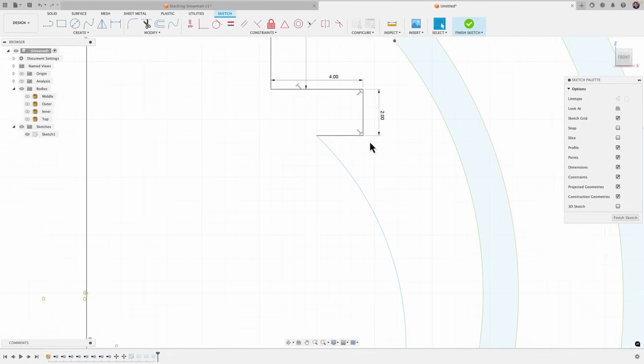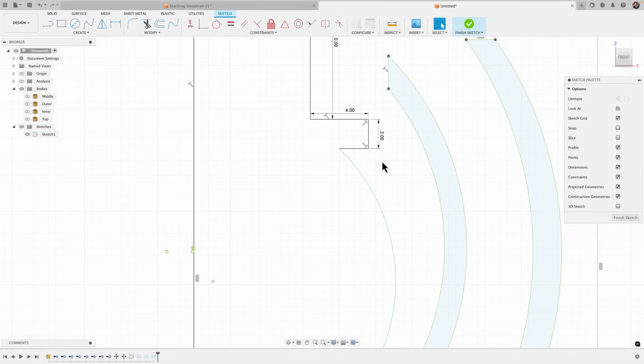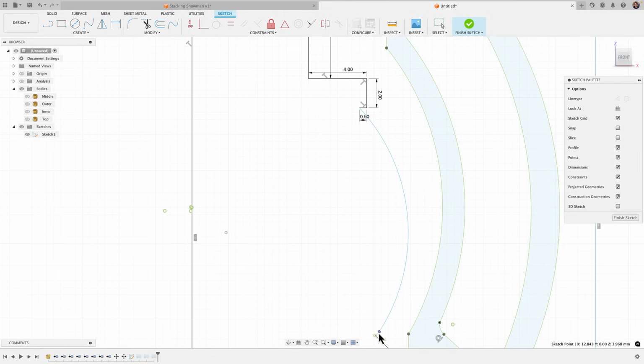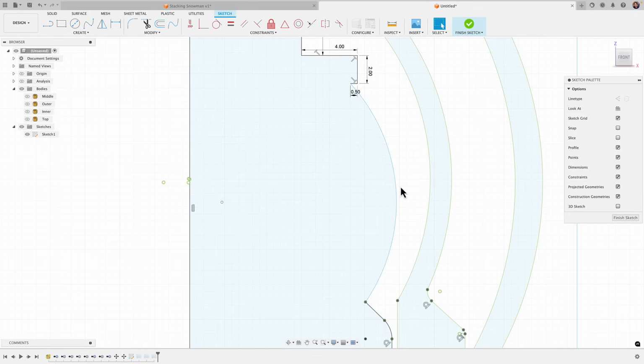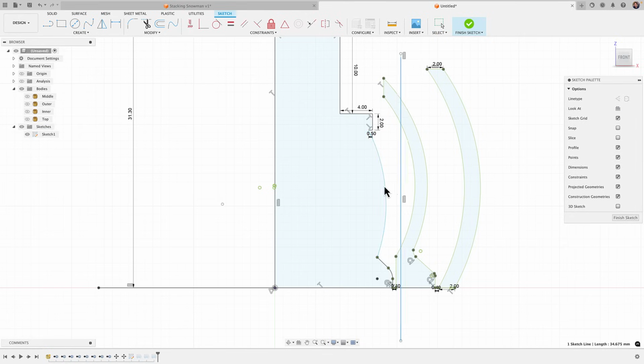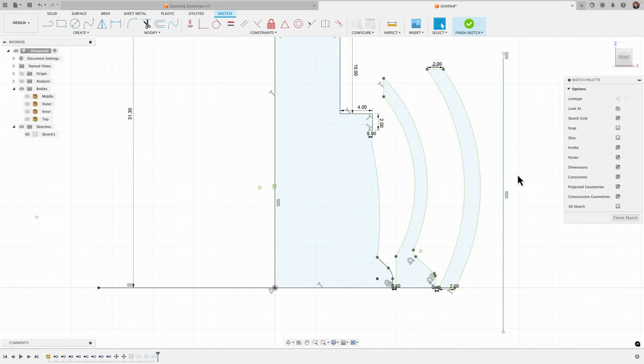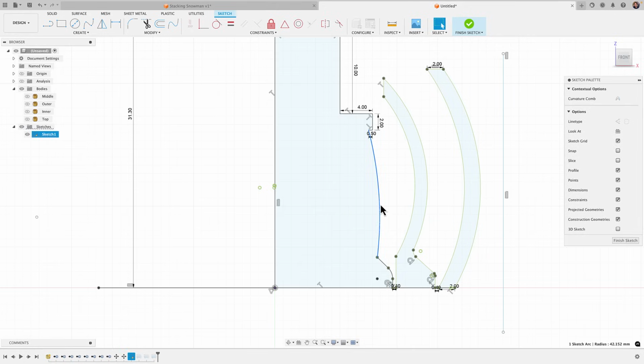I have another constraint here I'm worried about, because the way this prints, this is going to be an overhang, so I really am going to have to limit this to like 0.5 millimeter. Now let's bring this, it's coincident to that point. And so here, let me bring this line back. The cheeks there would have to be like this, and I'm not really liking that. That's too skinny of a face for a snowman, and I want it to be a little more round, so let me delete that.